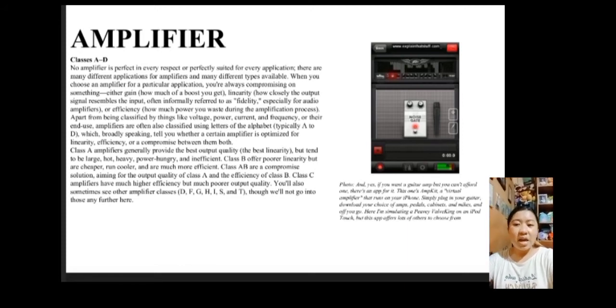Class A amplifiers conduct through all the period of the signal. Class B, only for one half of the input period. Class C, for much less than half the input period. Class D amplifiers operate their output device in a switching manner. The fraction of the time that the device is conducting is adjusted to a pulse width modulation obtained from the stage.